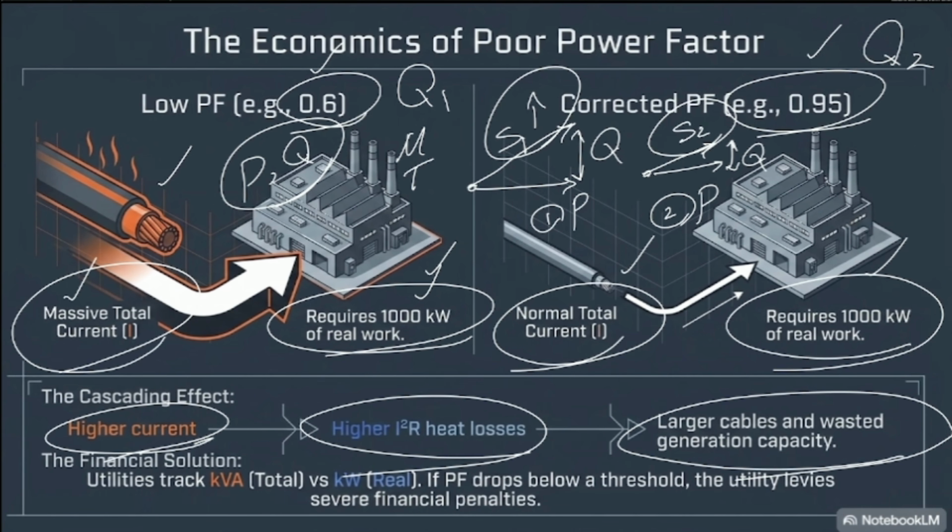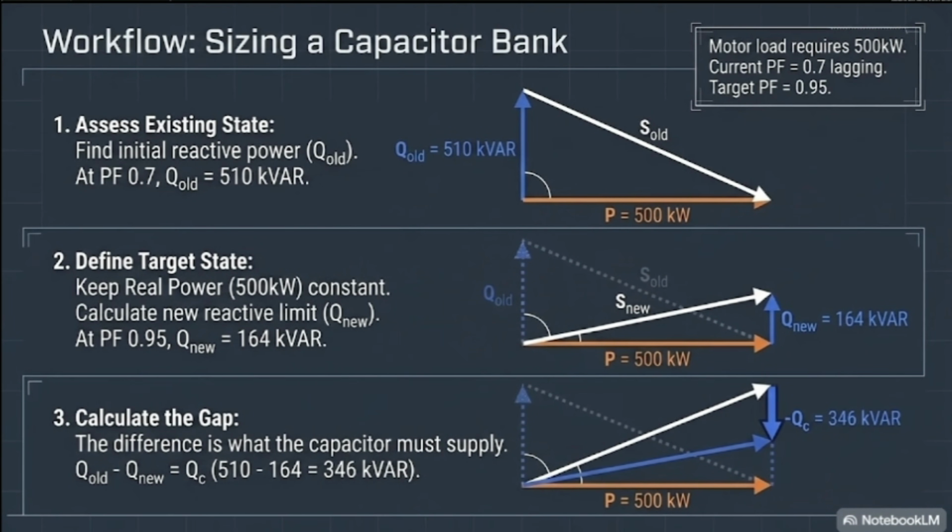That's why a high power factor is important to us. If I would like to give you a very common solution that factories use in order to compensate for the power factor, we are going to reach the capacitor banks.